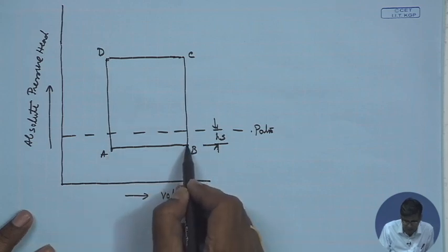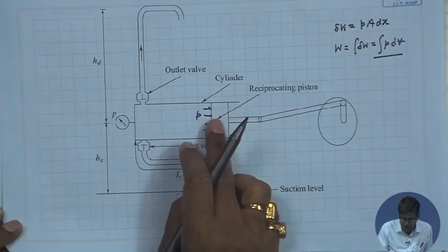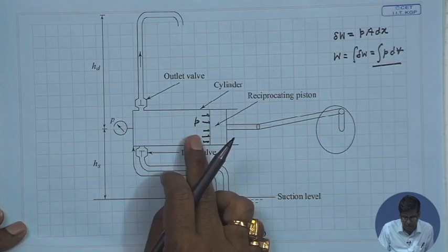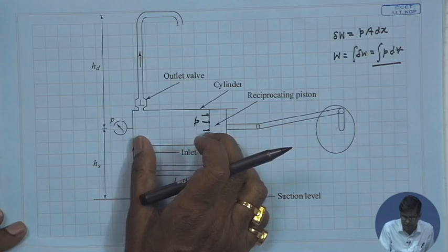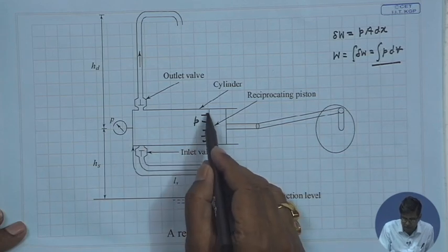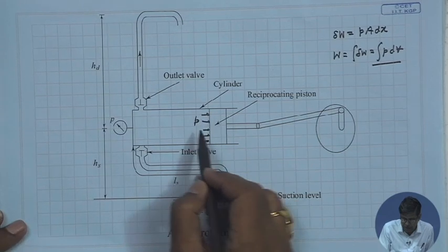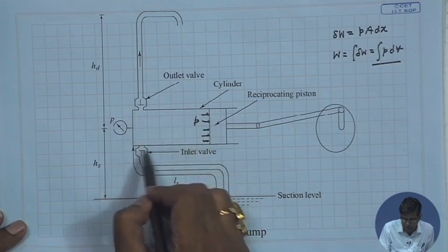Now, at the end of the suction, the piston pushes the liquid. If we consider the liquid to be ideally, fully incompressible, the property of an incompressible fluid is that it gets pressurized instantaneously without changing in volume. Why? Because if the piston pushes it, a pressure wave is generated which is transmitted upstream to pressurize the entire fluid.